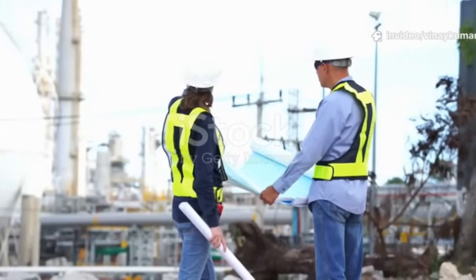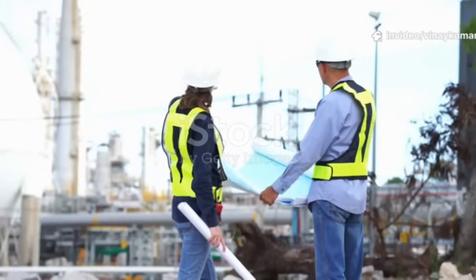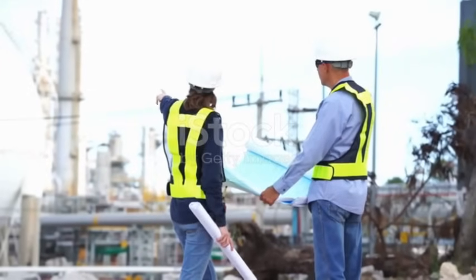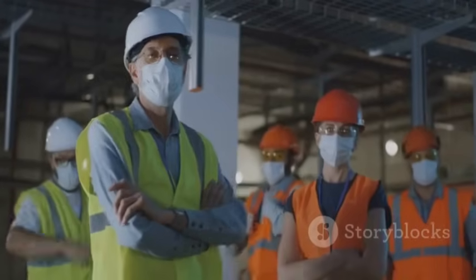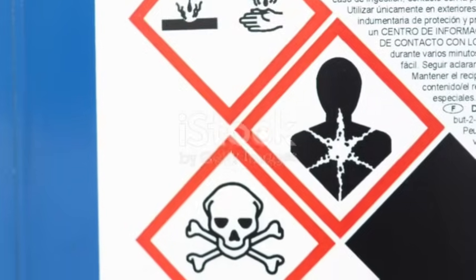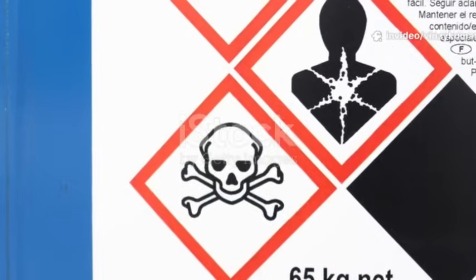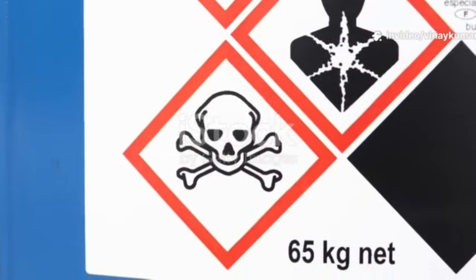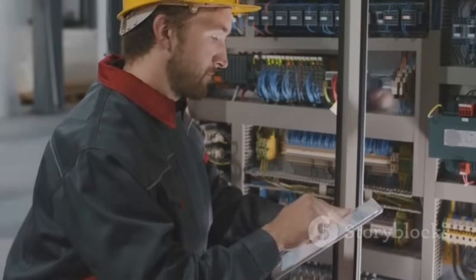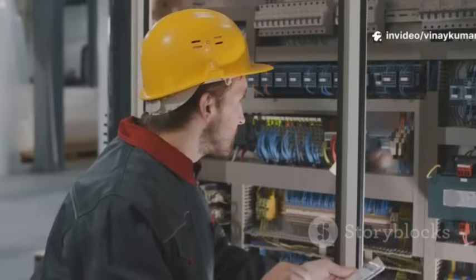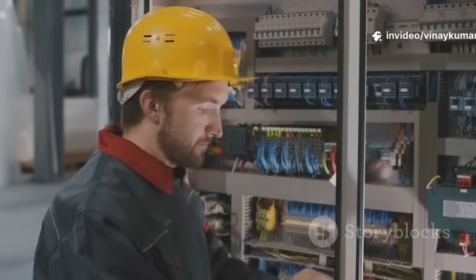You've designed a new process, or you've just completed a major modification to an existing one using your management of change procedure. Everyone is eager to get it up and running, but wait. Before you introduce hazardous chemicals into the system, there's one more critical checkpoint: the Pre-Startup Safety Review, or PSSR. This is the eighth element of PSM. The PSSR is a final verification to confirm that all the safety requirements have been met and that the facility is truly ready for a safe startup.